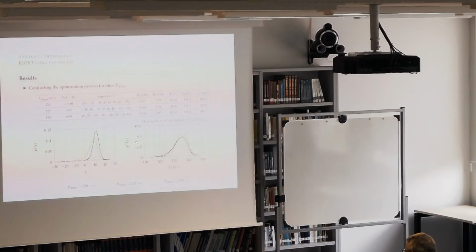But on the PDF of the flutter velocity, we can see that if I calculate my 0.1th percentile flutter velocity, this value increases with my design velocity. So I can say that I can gain in performance when I increase the value of the design velocity during my optimization.